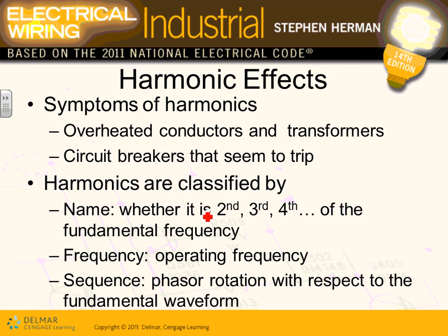Okay, symptoms of harmonics. How do you know that you have harmonics? Overheated conductors and transformers. If your conductors are overheated and burning, the lugs are burning, especially in the neutral, and your transformer dies prematurely on you, and you're not overloading the transformer or the conductors, guys, that's an indication, Adam, that you have a harmonic problem.